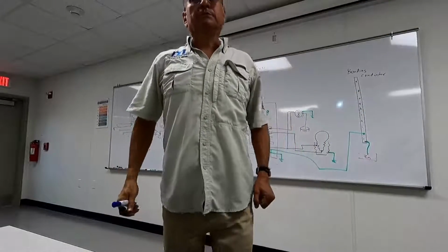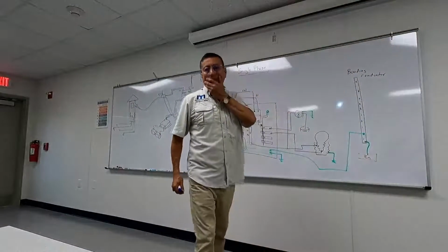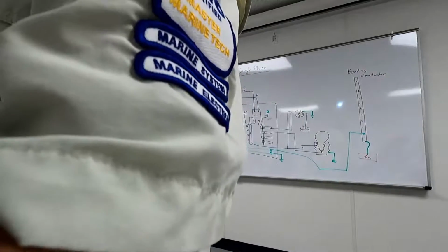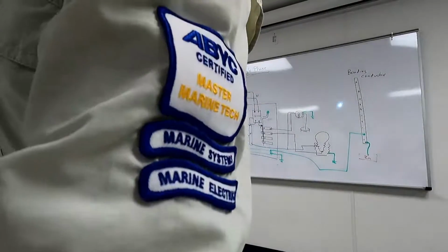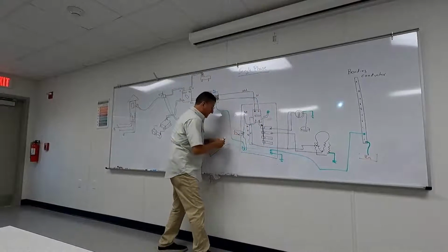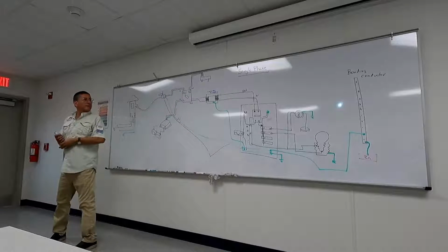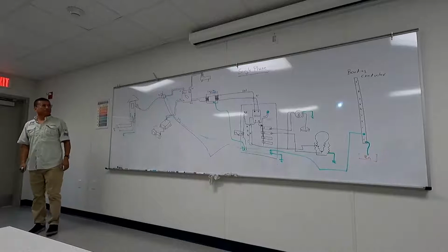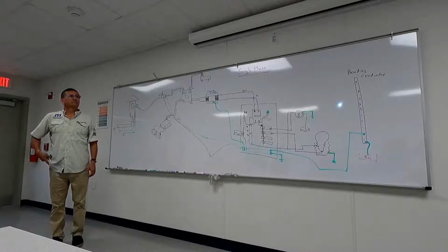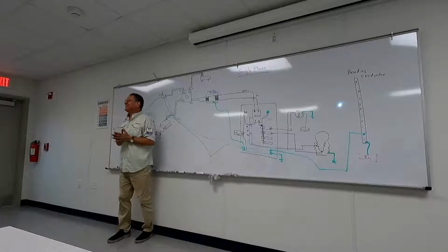What do you think would be the effects of having reverse polarity? What would be the damage you would cause? It's 2.5 kilo ohms. What's connected to the neutral at the source? Ground. So if I had a reverse polarity, you just energize your bonding system. That's the next. Pay attention.